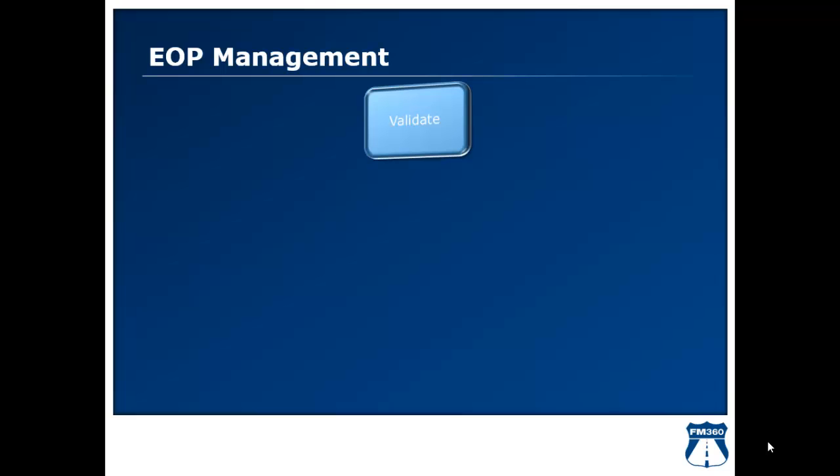Second, take advantage of any and every opportunity you have. If there is a scheduled outage or even an unplanned outage, go and execute some of these EOPs. If there's a construction project, it's a great time to take advantage of the facility being offline so that you can perform and validate these procedures.